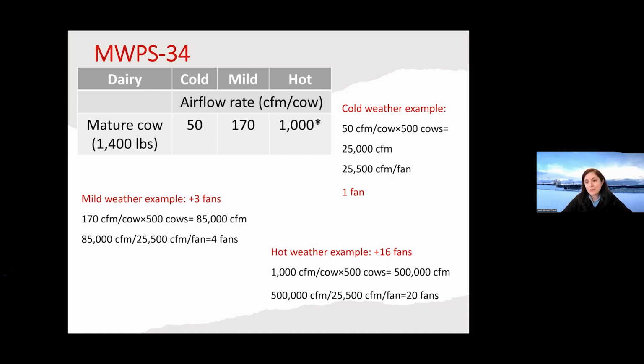So it really depends on the volume of the barn. Maybe the stall size is constant in each barn, so it depends on how many animals you put. Maybe the width and the length of the barn don't change, but the height of the barn varies a lot. Some barns have a big roof structure, so the volume is bigger and it is harder to pull air through. If it has a false ceiling, if it is flat, with a lower height, it is easier to pull air through.